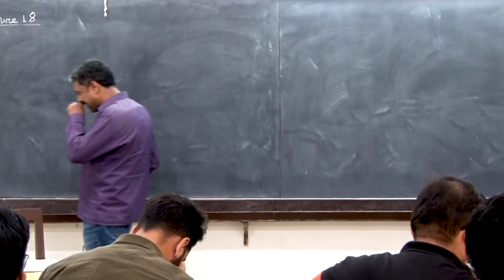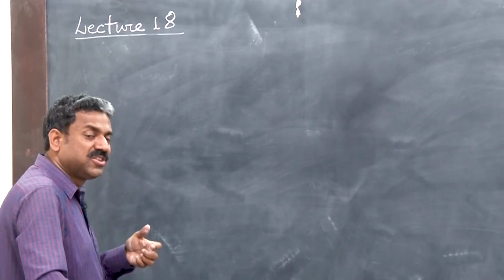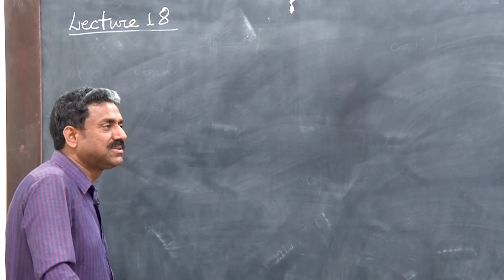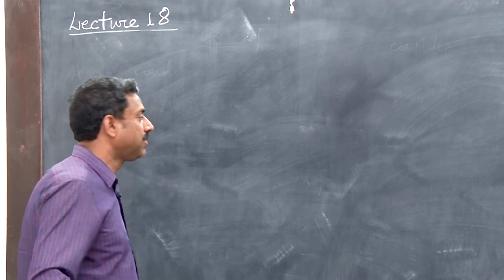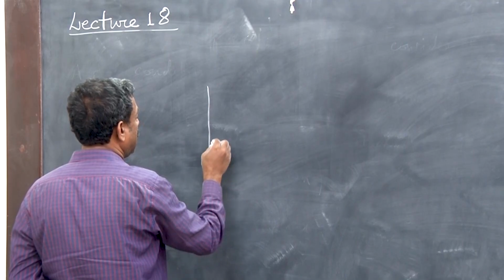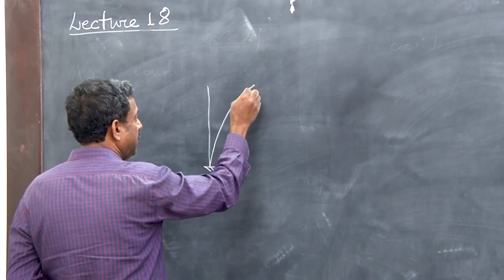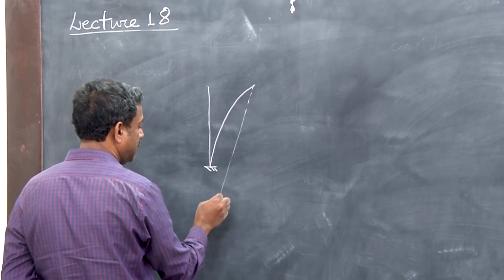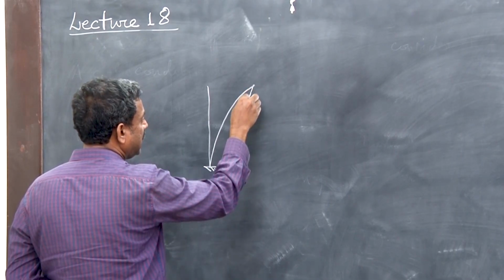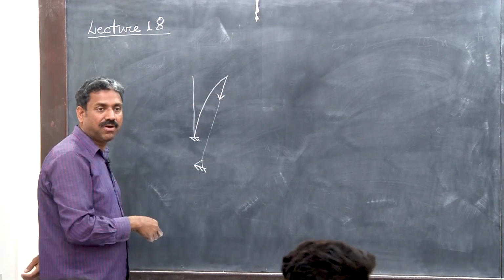So what we are considering is the follower force. It is a non-conservative force, but please note that just because a force is a follower doesn't mean it is non-conservative. For example, if you have a column that is fixed to another support, causing the force to always pass through it, this is not an example of a follower force.